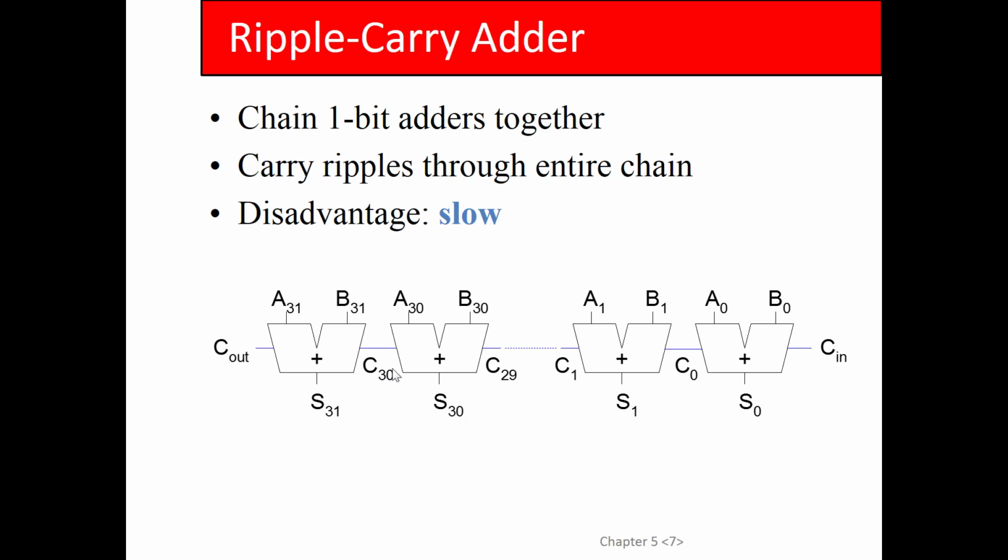So this way I break the carry chain, but I still need to look at all these generate and propagates from these guys. But check that out. I can calculate the carry in now in 2 gate delays because this is product of sums. Sum of products, right? Now I'm not including the gate delays it takes to calculate generate and propagate, but those are pretty simple.